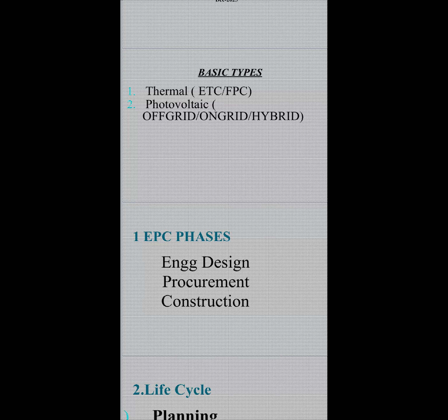What is BESS? BESS means battery energy storage system. It is a large battery bank which has battery management software, BMS. We call that a BMS, battery management system. It is a complicated both hardware and software. And then you have a cooling system. Most of the times, if it is a smaller one, it's an air-cooled system.